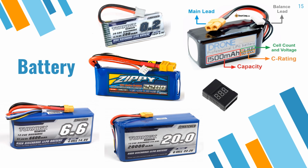A cell represents 3.7 volt on average, so that means that this battery has a total average voltage of 14.8 volt. Of course, a fully charged battery has a higher voltage, and a fully discharged battery has a lower voltage than the average voltage. The next thing to consider is the capacity of the battery. The capacity basically represents the amount of energy stored in the battery. So the higher the capacity, the more energy the battery can store, and the longer the flight time of your drone can be.